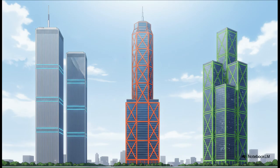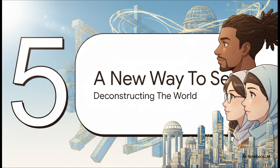As you can see on the left, you've got the frame tube of the original World Trade Center. In the middle, the iconic X-bracing of the braced tube, which you see on Chicago's John Hancock Center. And on the right, the bundled tube of the Willis Tower, where multiple tubes are basically lashed together for just incredible stability.